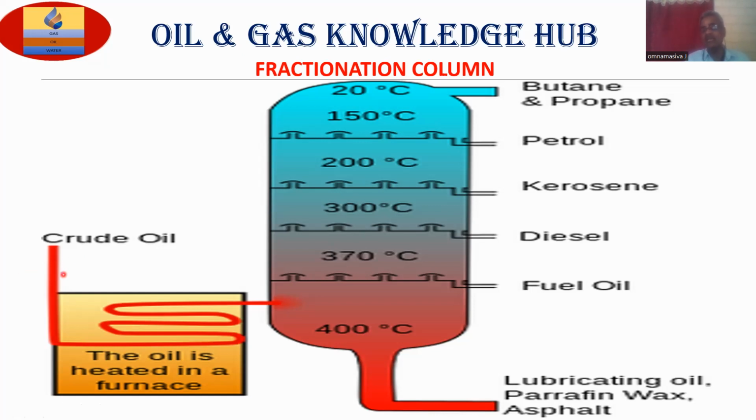So once it enters the air preheater, first it will come to the air preheater convection box. In the convection box, there will be a studded coil. Through the studded coil, it will pass. That means it will be preheated, because this heater will be operated above 455 degrees Celsius. So heat transfer will take place initially in the studded coil, around 70, 80, 100 degrees Celsius.